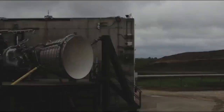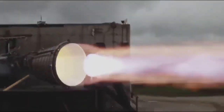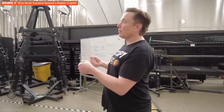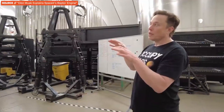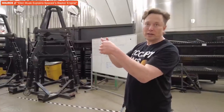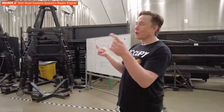With everything intertwined and interconnected, one small change in one part of the engine can have this huge ripple effect on absolutely everything else. In the case of Raptor, you've got an oxygen power head and a fuel power head, and they're different shafts, obviously, and you've got 2 turbines and 2 preburners. And they're cross-feeding one another.